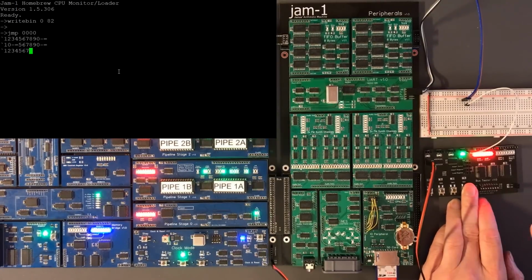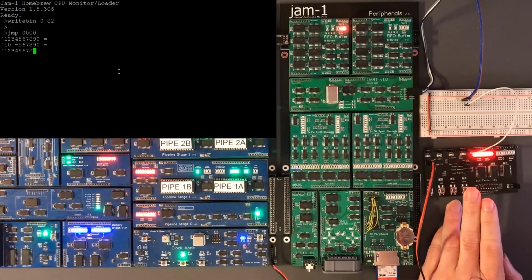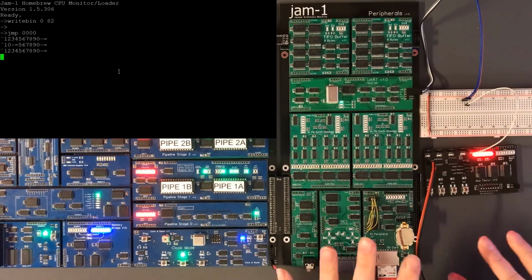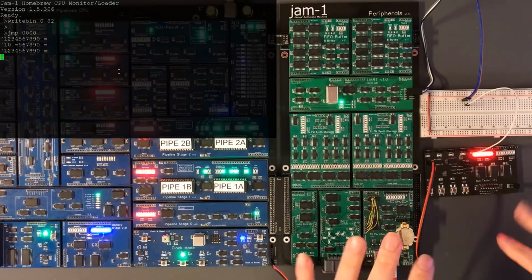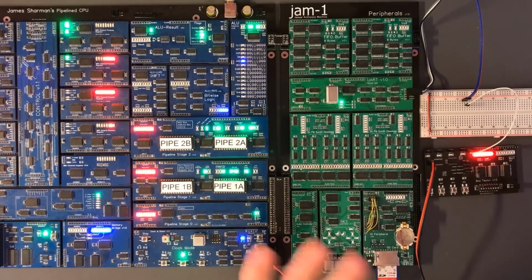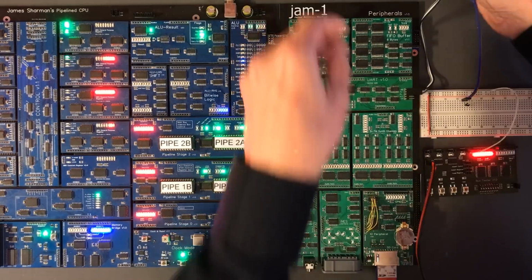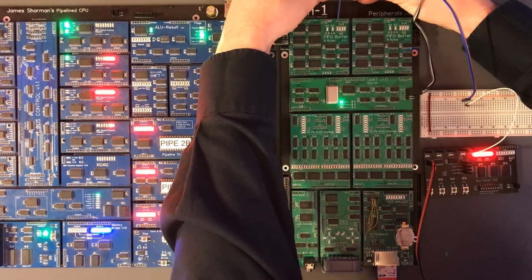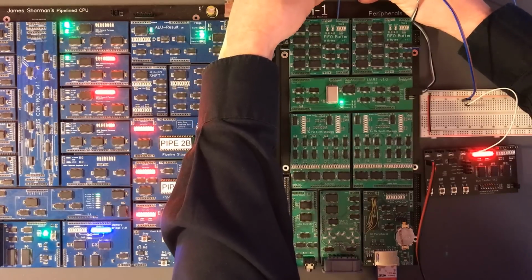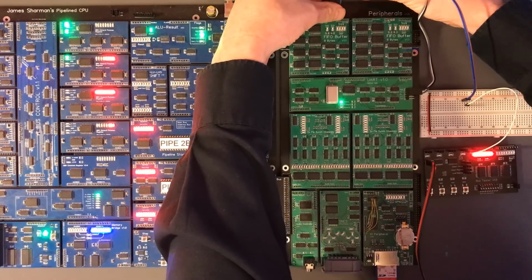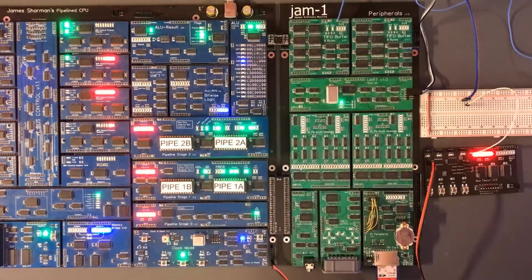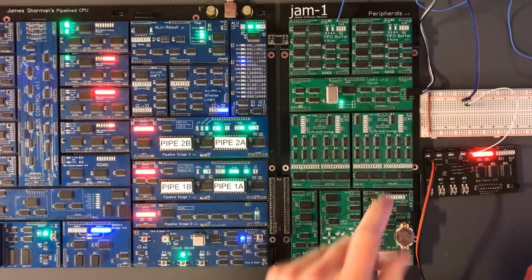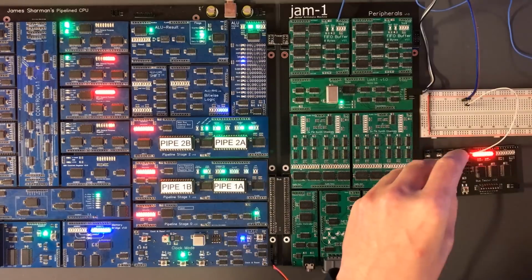I've pushed the button down when I got halfway along. Now I release it and bingo, the rest of the bytes come in. What we need is to repeat this process but have that signal generated automatically. I'm going to come in here and try and grab that top bit. So we've got 4 bits of output and an 8-byte buffer. So the binary representation of 8 is 1 followed by 3 zeros. So when the buffer's full, this top line goes high.